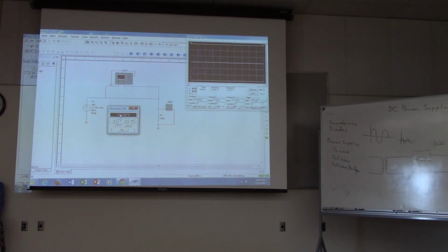And then the book asks you what type of voltage the DMM is measuring. So what it means is, are we measuring a peak voltage or a peak-to-peak voltage or an RMS voltage, or what are we measuring? What do you guys think? RMS. RMS, exactly. And we can tell because this voltage that shows up on the meter is exactly the voltage that is labeled RMS on the page, right? So that's a pretty good tip-off. So you're going to do that, and then you're going to pause the simulation and draw your wave in your book.